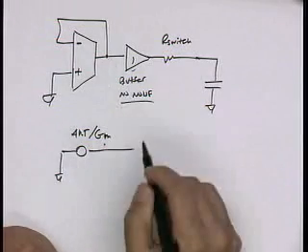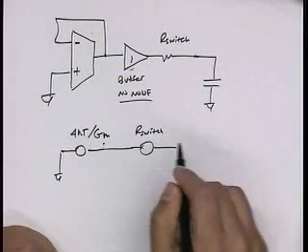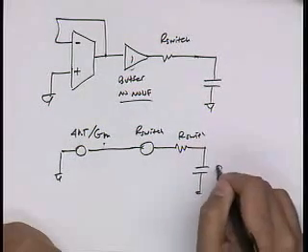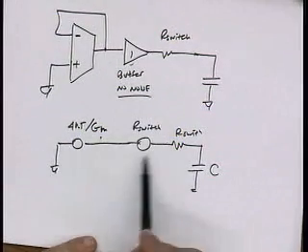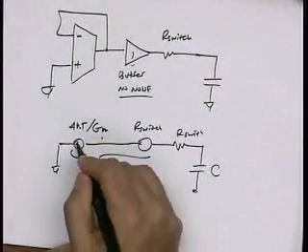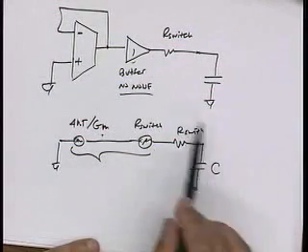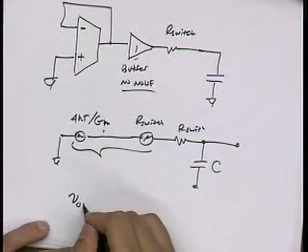Then I don't have any noise in my buffer, so then I'll have the noise of the switch, and then R switch, and then C. If I now look at the noise generated by my noise generators, and I integrate from 0 to infinity with a low-pass transfer characteristic, what do I get? Do I get kT over C? Why is it more?